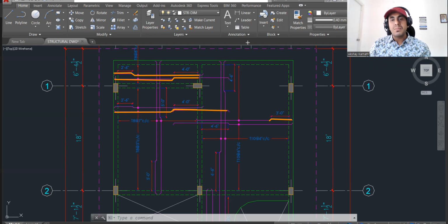But since I have a slab here, when I'm giving reinforcement for this particular slab, I need to start like this, give like this, and go like this. Instead of giving two different bars, I'll apply a simple logic: I'll provide a straight bar up to here. Simple. But why is it at the top? Because we know there is a negative bending moment happening in this portion. A negative bending moment means you need to provide top reinforcement. That is why the bar will be taken at the top.